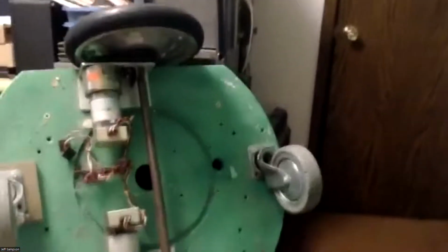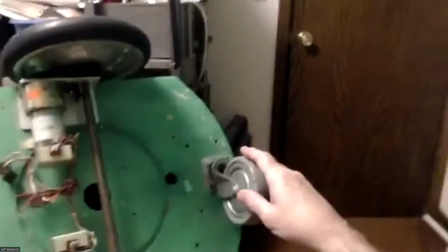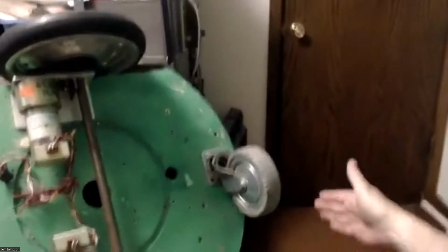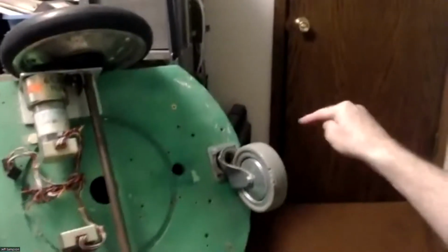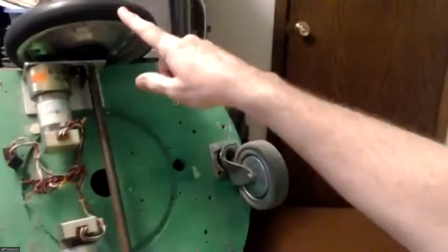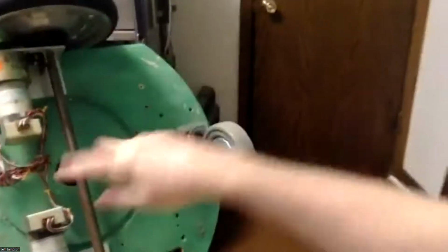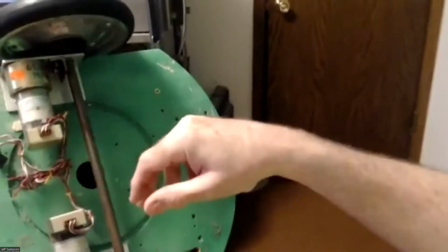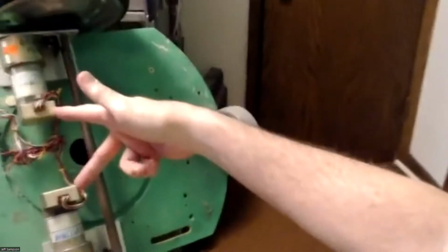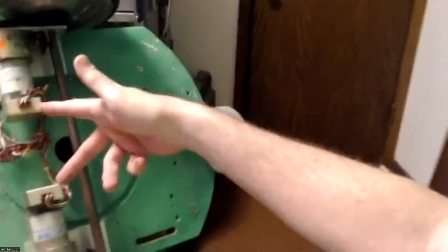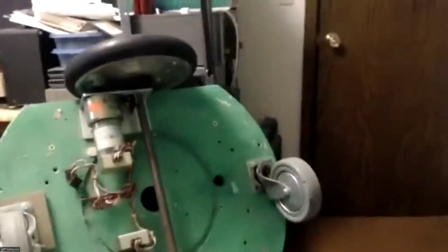The other thing is, without modifying this at all, just to prove this out, I could take these two caster wheels off and just run a frame that sticks out the front and put my axle for my Ackerman out here. Or I could just put a tricycle, a single wheel that's steerable. Because all I want to do is prove that having the two DC motors and the encoders on them, number one, it will drive around, and number two, I will still get valid odometry by simply running these two motors in parallel or running them in series. I'm thinking they should equal out, and everybody should be happy on that.